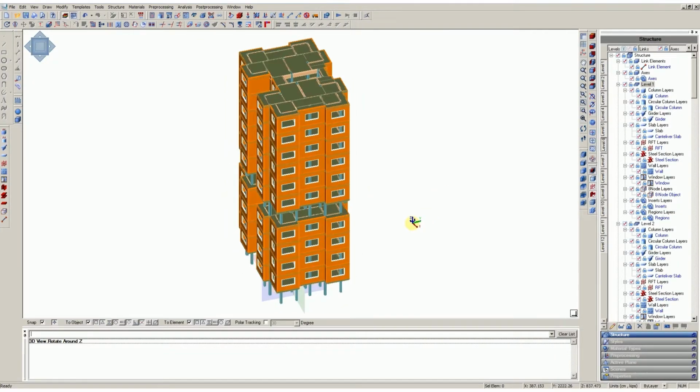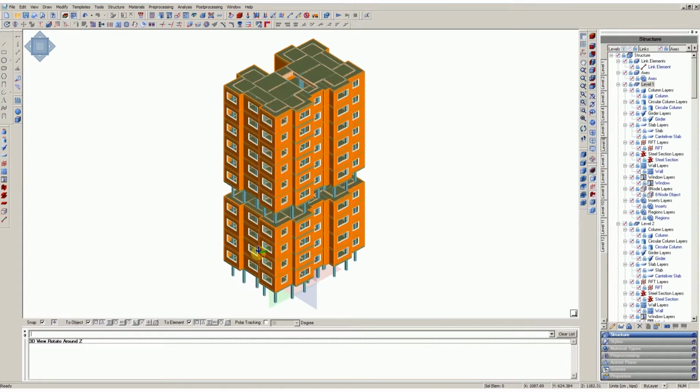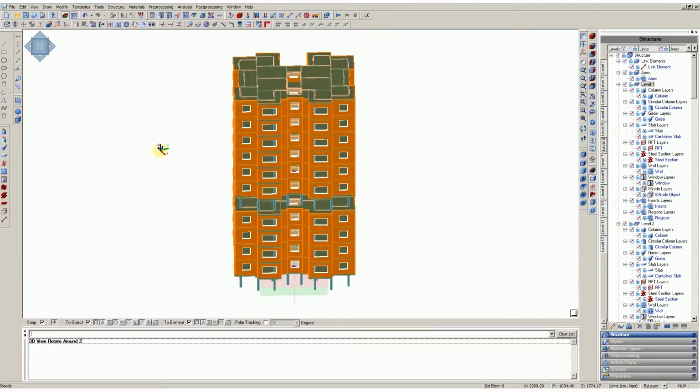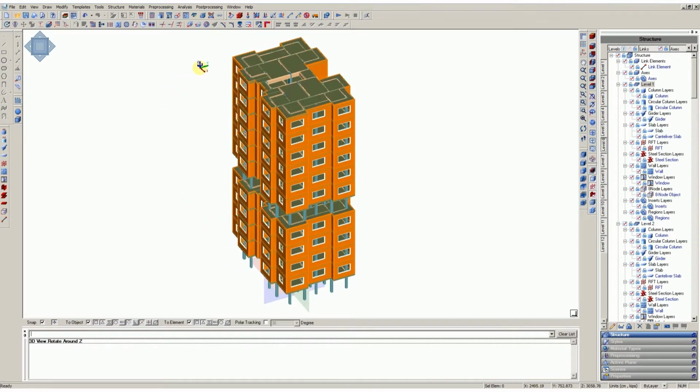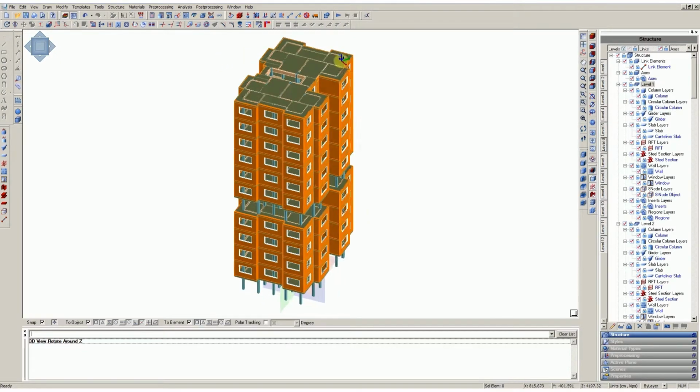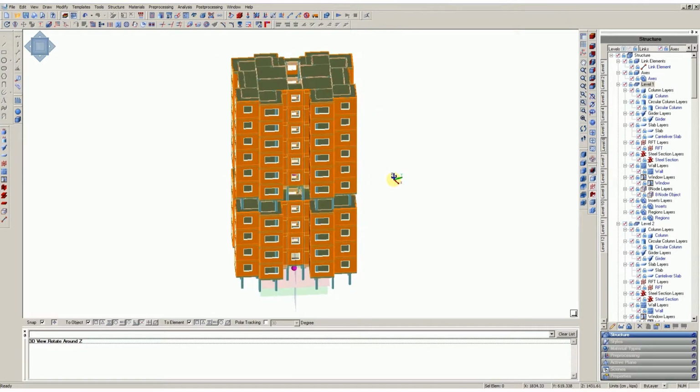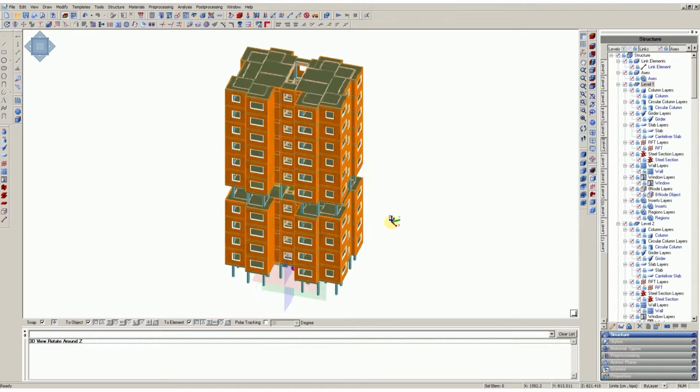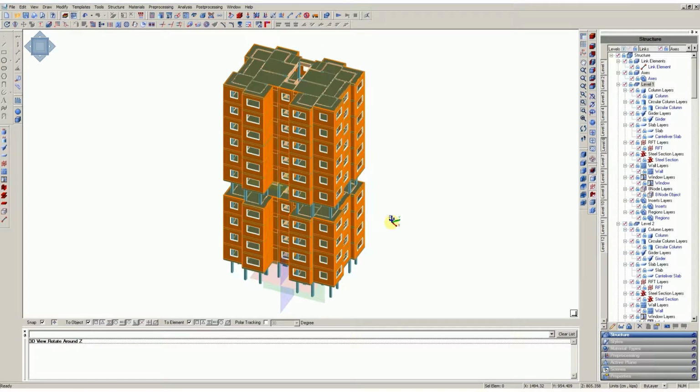Earthquake loads have a significant effect on high-rise buildings, especially if there is a soft story. A soft story is a structural design in which there are no walls, only skeleton objects exist. Rotation of the columns in the soft story is a very important issue when the structure is subjected to seismic loading and an important factor to consider when using dynamic analysis.